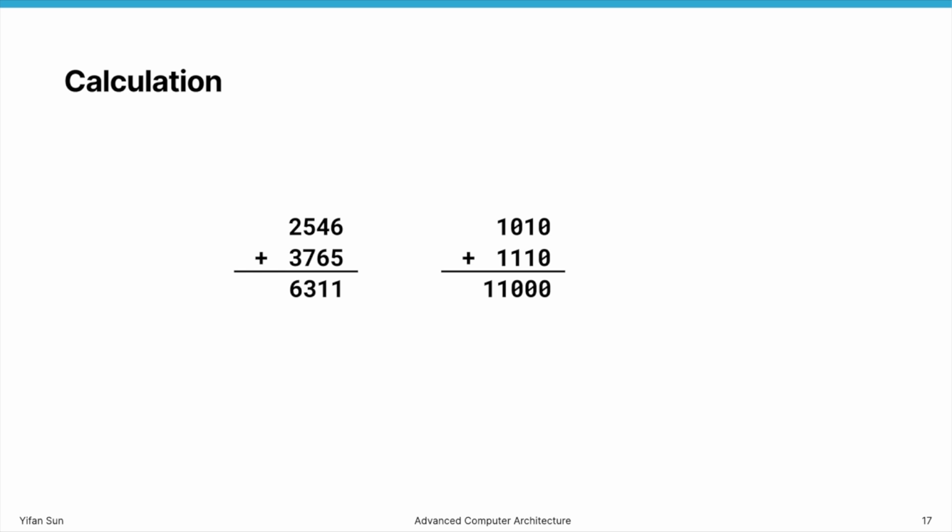If we know the rule of how to do the sum operation of two digits, then we can write down all the possibilities and do the calculation: for this input we get this output, for this input we get that output. Then if we can list all the possibilities, we can express them in combinational logic. We can calculate them with a circuit.